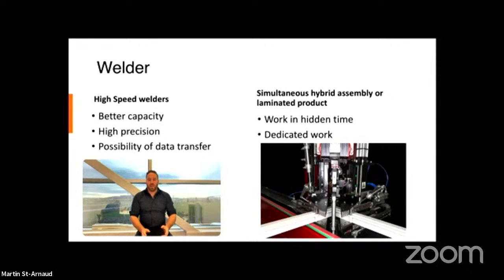You could also, if you have a 3 light, have the same system working, making 2 different sets of holes on each side. Just keep in mind that if you're putting this hardware between the 2 heads, you're making your minimum weld a little bit bigger. So if you're going to be using the same welder for frame and sash, I would not recommend having that installed on a welder.